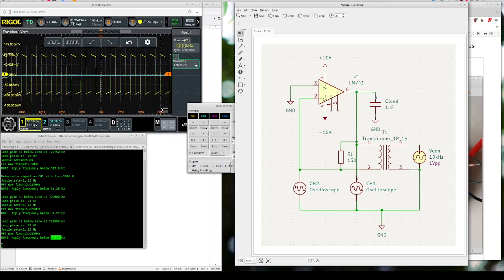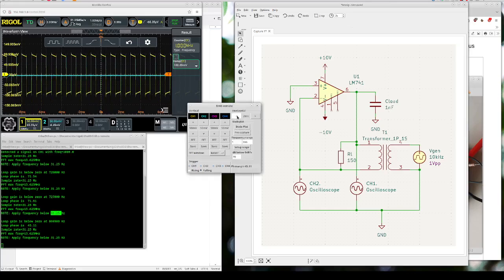There's one thing I want to show, that I can also make it unstable. The op-amp might become unstable if I put a capacitor at the output, and that would lower the phase margin. Now give me some time, then I'll plug in the capacitor. Okay, so that has been done. Now everything looks the same from this distance. And I plot again.